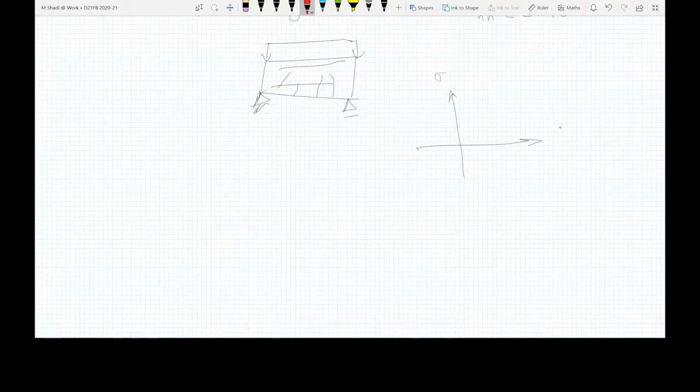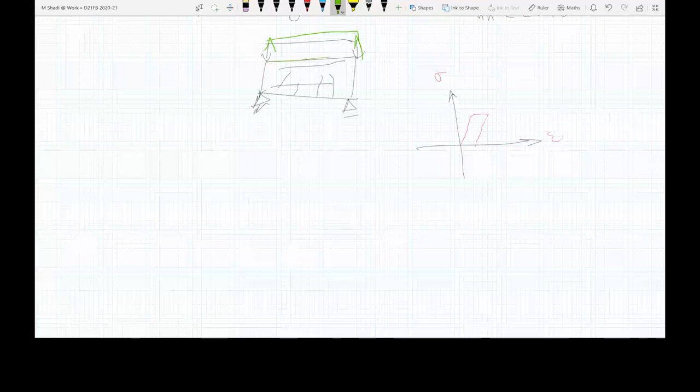This is the stress, this is the strain. So you start loading, and this beam is going to yield, start to crack, and deformations are going to become big, and then you release the stresses. This is going to come back to zero stresses, but it is not coming back to zero strain. There's going to be some residual strain in there. Now, assume that you switch the load, and instead of applying the load downward, you release the load downwards and you apply the loads upward now.